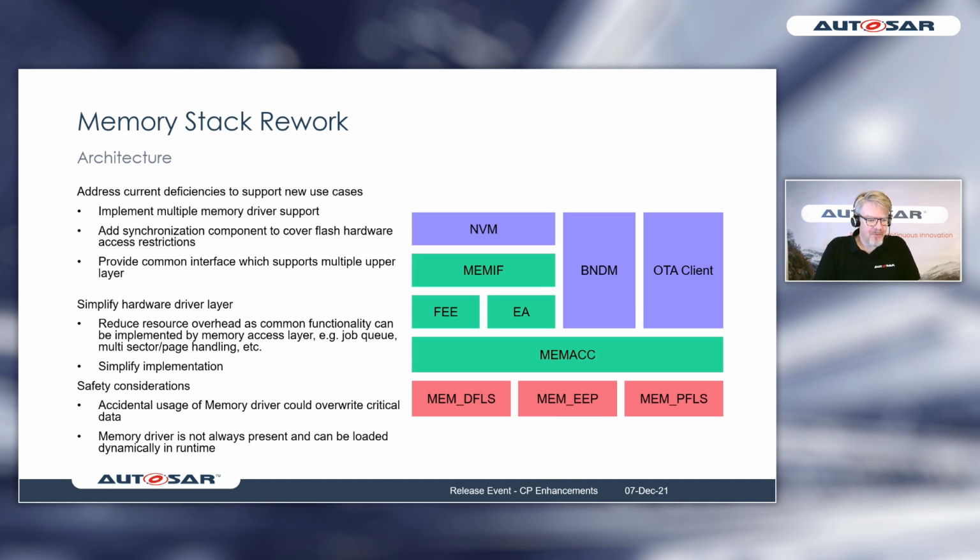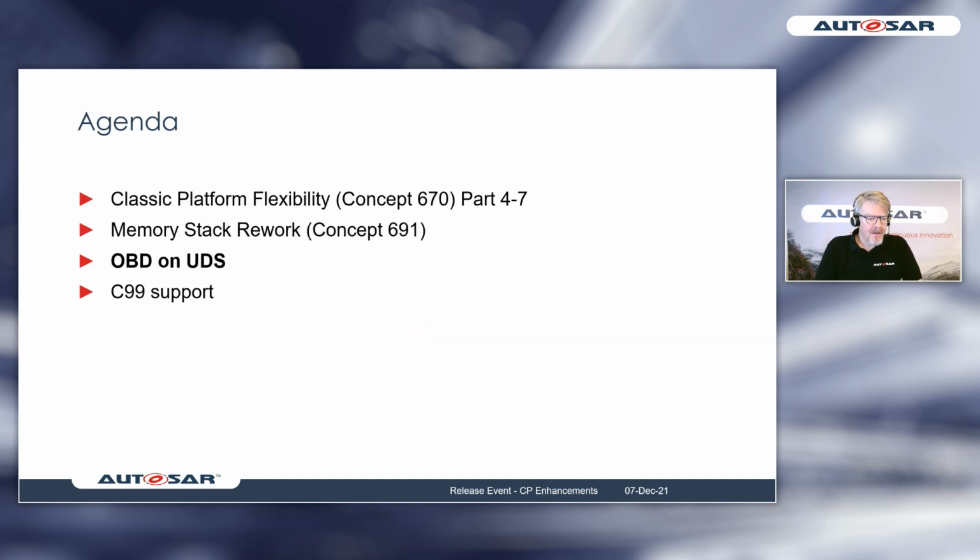Therefore, this memory driver can be stored somewhere else, where it is not normally accessible, and then loaded dynamically at runtime to make it available, for example, for the OTA client to write to the program flash. So this was an essential update, our refactoring of the AUTOSAR memory stack, which was demanded in the market for a long time. But it's not the only enhanced topic.